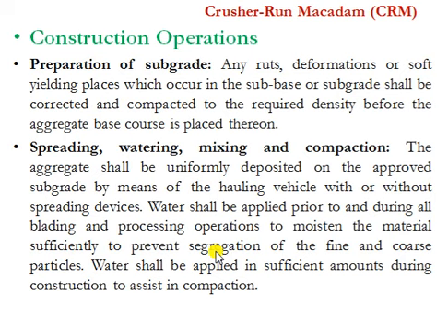The sprinkling of water also helps in compaction. With more water content, the compaction of the aggregates becomes easier, and hence water is applied in sufficient amount during the compaction, which makes the compaction easier and the material will become denser with the compaction.